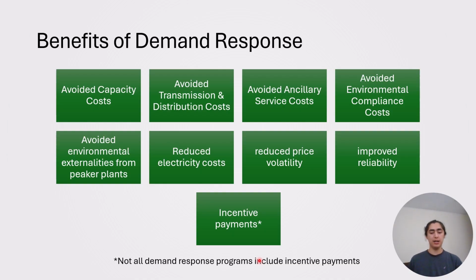And then reduce electricity costs. This is a significant one and one worth noting. If we can shave demand, then the price facing all rate-paying consumers goes down. This can introduce some kind of risk of free loading, where we have a handful of households and businesses participating in a demand response program, shaving the peak and avoiding huge spikes in the wholesale price, but the retail price that is facing all ratepayers goes down as a result, and people will benefit even though they don't participate in demand response. Also, there is reduced price volatility in wholesale markets and improved reliability as well.